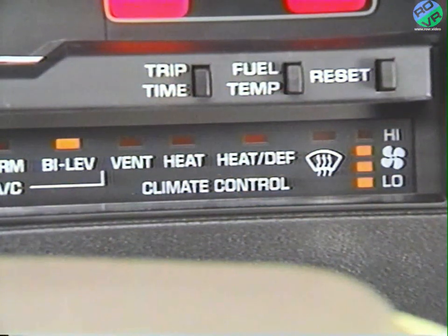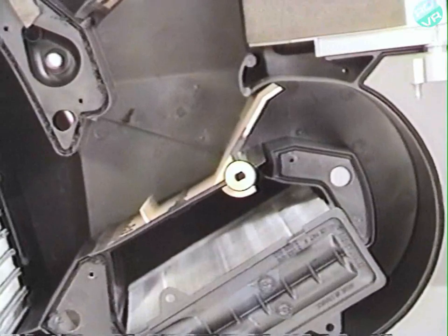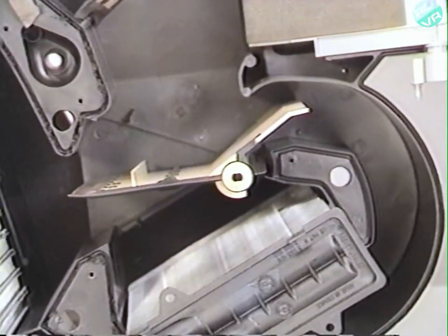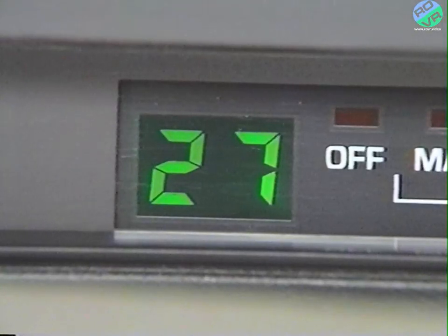If sub-mode 1 is entered, however, the bi-level indicator will light, and the ACM will position the air door to correspond to the present temperature setting of the system. At the same time, the temperature display will indicate the feedback voltage from the air door without a decimal point. This voltage reading and the readings to follow will be used by the ACM to calculate the travel in degrees. It is this final reading that indicates whether the air mix door is working properly.